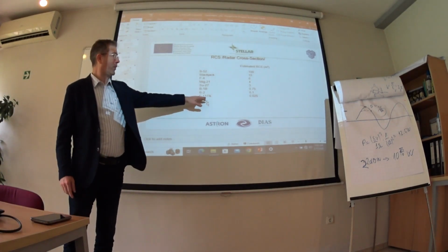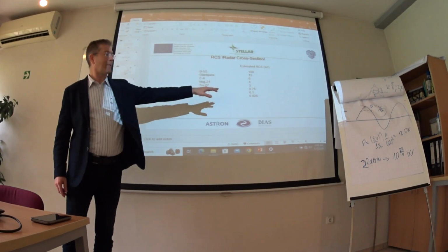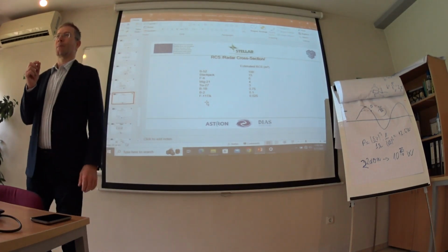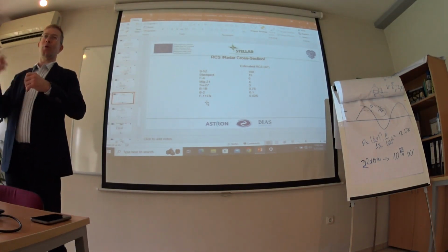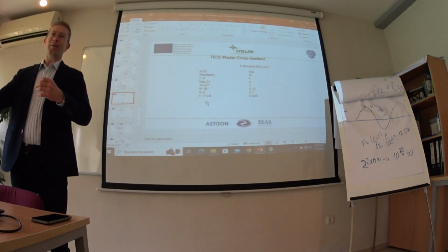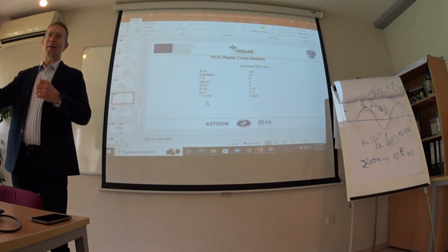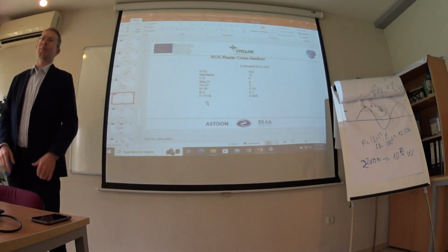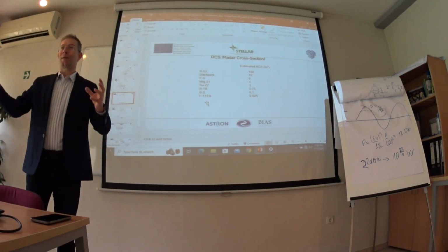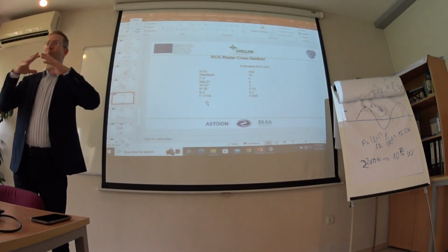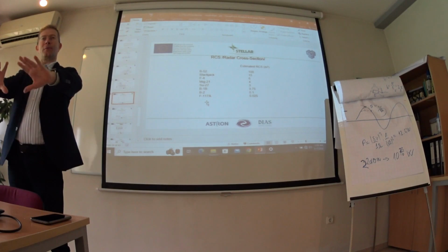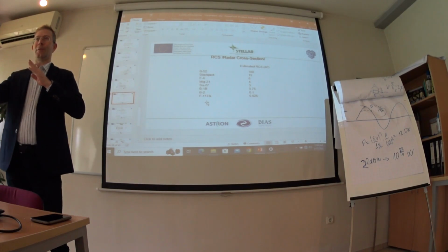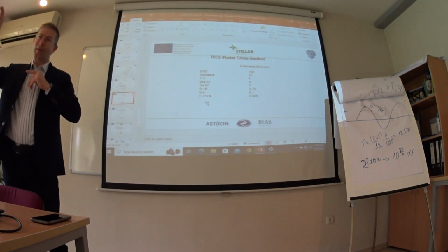And F-117 is almost invisible to radars in a specific frequency range. But that's why smart people develop broadband radars, and you expect that the target will be lit up in some frequency. Or use multi-static radar, because if the shape of the plane scatters the waves toward another direction, not toward the direction of the main radar, you can see it from another location, see, oh, this guy is there.